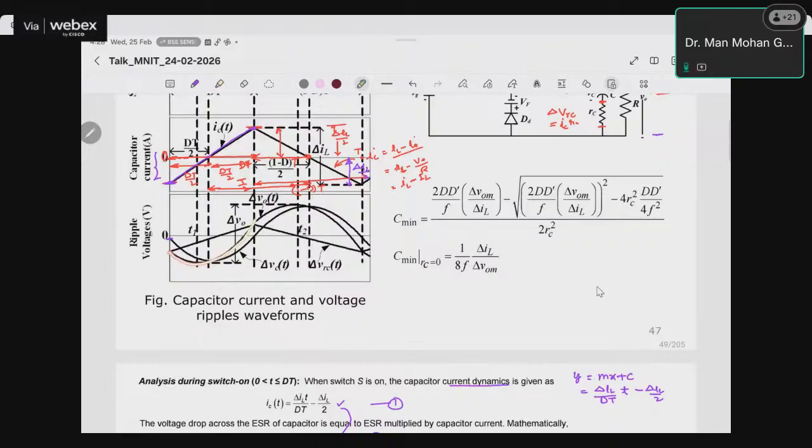here, right? Now we are finally interested in obtaining the del V naught, right? Del V naught. So what is that? It is the difference. So this voltage will have certain minima, right? But we do not know at what time it is getting minimum value. Similarly, during turn off time also, this output voltage had certain maximum. We do not know at what value of T2 it is maximum. We do not know at what value of T1 it is minimum, right?